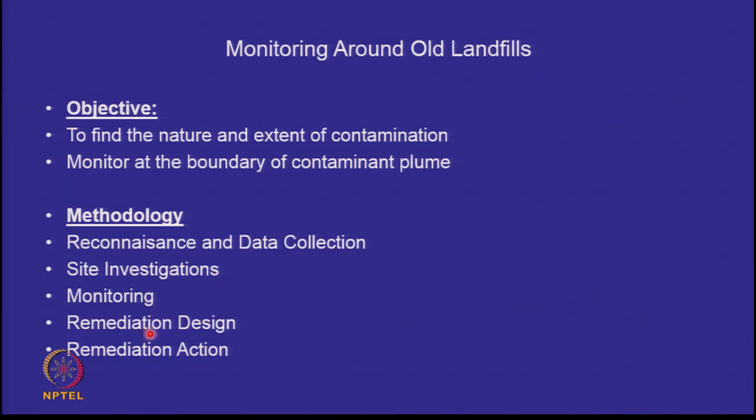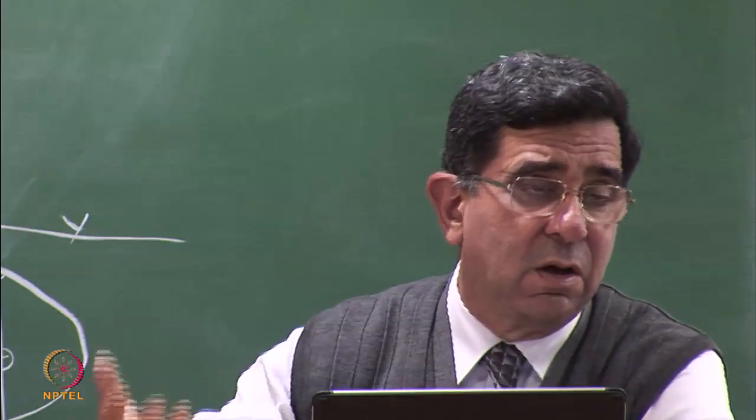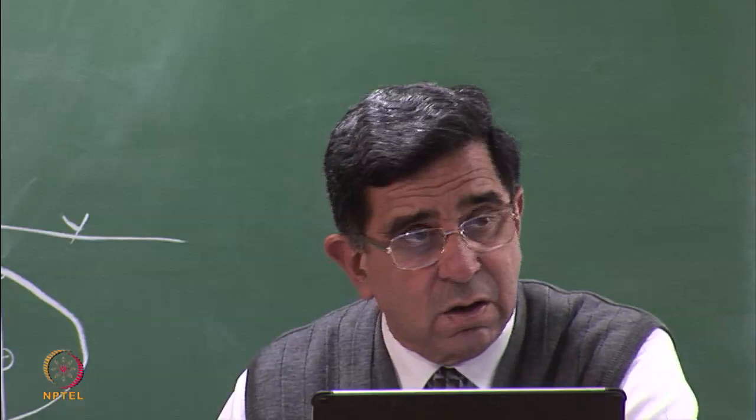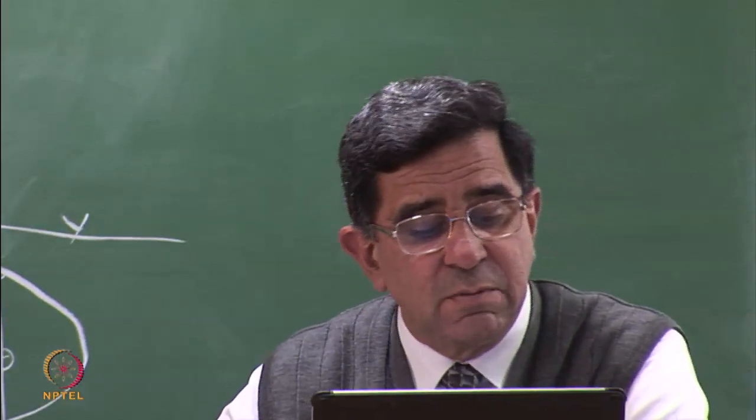And then you will do a remediation design. How are you going to remediate? What has to be removed? What is the kind of treatment system you want? Are you going to pump out the water? Are you going to inject good water? Are you going to do in situ bioremediation? And then you have to take remediation action.